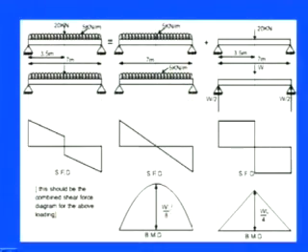It is very interesting if you want to calculate those things. On top of that, you can see that our problem equates to one problem by the UDL plus one problem by the point load. So we can simply analyze those. In the bending moment, if you go to the previous slide, you will find that the maximum bending moment was WL by 4 due to the 20 kilonewton point load, plus WL square by 8 due to the UDL of 5 kilonewton per meter, and we can calculate those. So we have the shear force diagram for both things and the bending moment diagram for both cases.